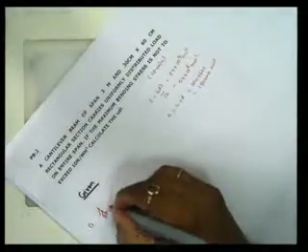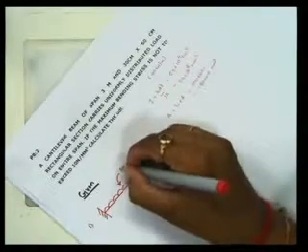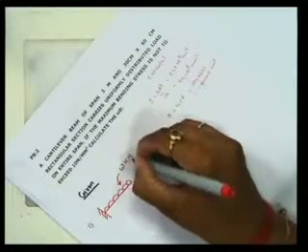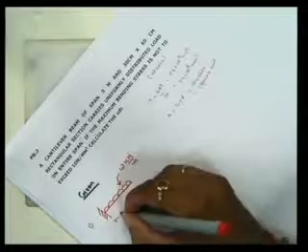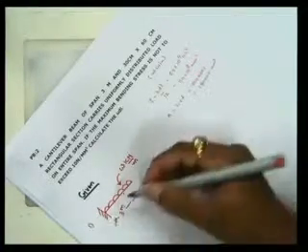From the cantilever beam, we can show that it is having a UDL. So I can write down over here UDL. I don't know the intensity, so I will write W kilonewtons per meter. And they have given you the span, the distance between the end point and the support, that is given as 3 meters.